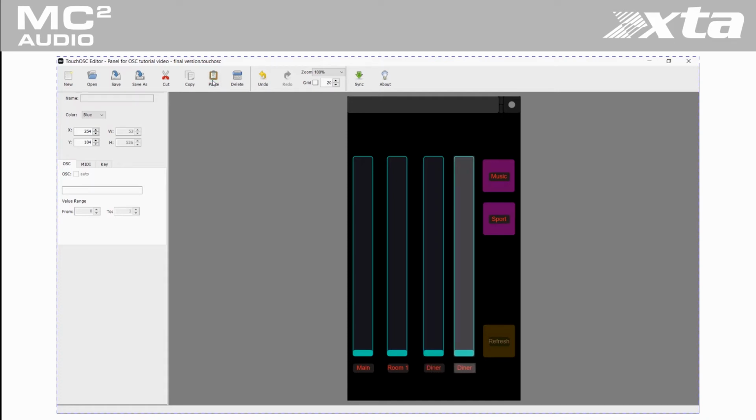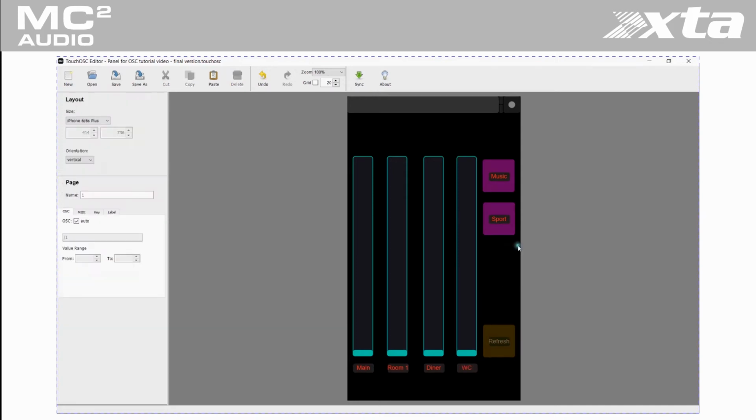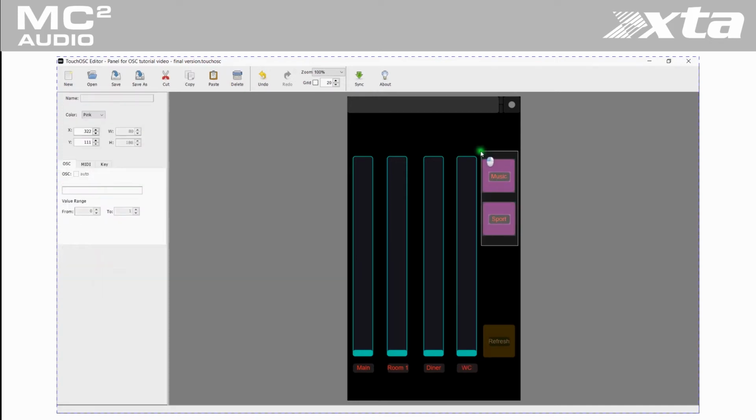Level controls can work from minimum to maximum or be a centered type. You can also specify the upper and lower gain range, i.e. set a volume window you want it to work over. The restrooms and corridors are on aux4 on our amplifiers. You'll notice the gain range in this application is set from -40 to -6 dBs. If these level controls were stereo 2-channel controls, we must remember to gang them in the amplifier settings.